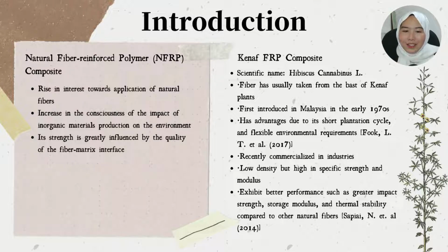Kenaf, with its scientific name Hibiscus cannabinus L, is an herbaceous plant that was first introduced in Malaysia in the early 1970s. Compared to other natural fibers, Kenaf has advantages due to its short plantation cycle and flexible environmental requirements. Kenaf fiber is usually taken from the bast of the plant and has recently been commercialized in industry as natural fiber reinforcement for composites for its appealing mechanical properties such as low density but high specific strength, impact strength, storage modulus, and thermal stability.